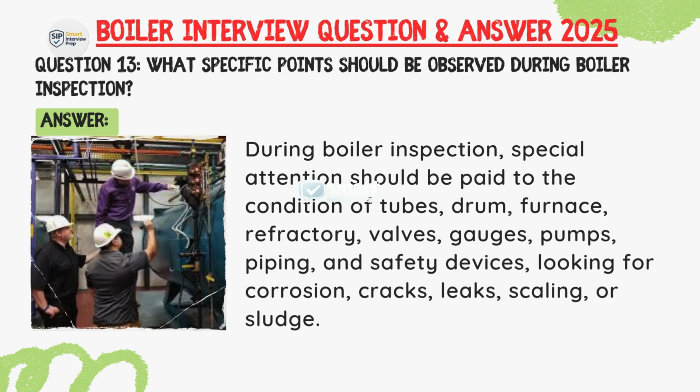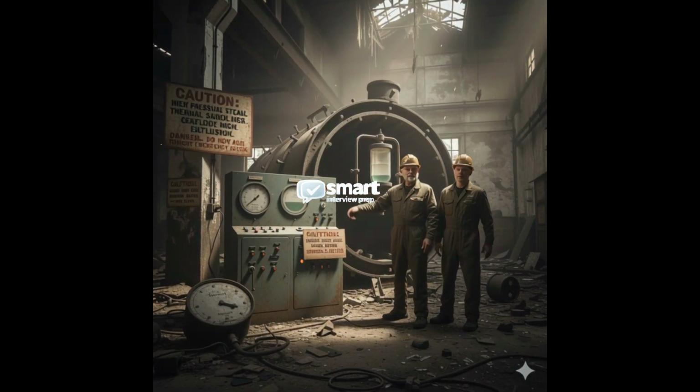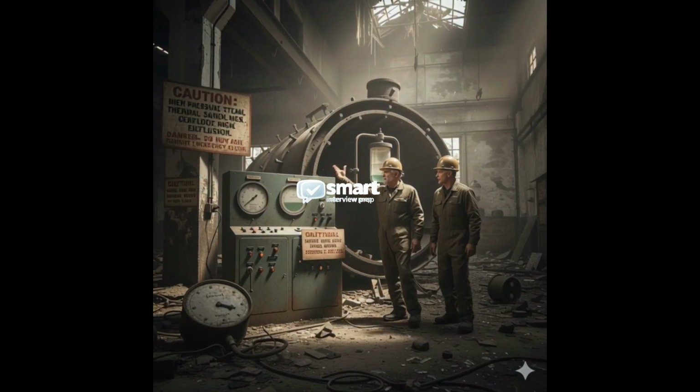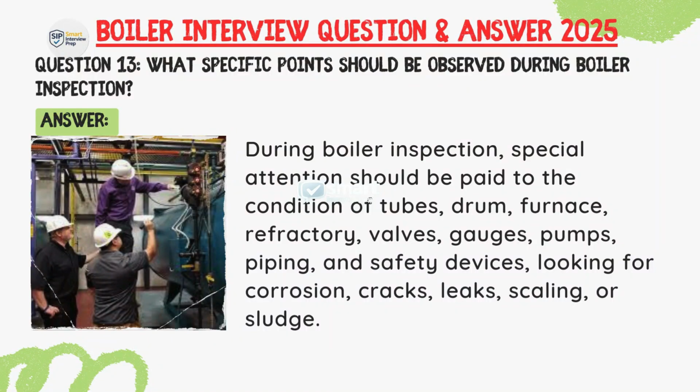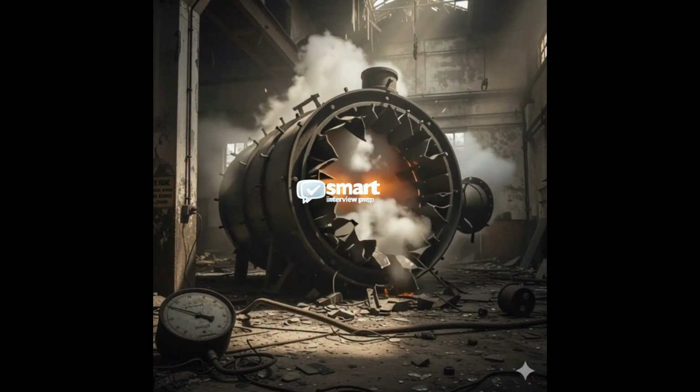Question: What specific points should be observed during boiler inspection? Answer: During boiler inspection, special attention should be paid to the condition of tubes, drum, furnace, refractory, valves, gauges, pumps, piping, and safety devices, looking for corrosion, cracks, leaks, sealing, or sludge.